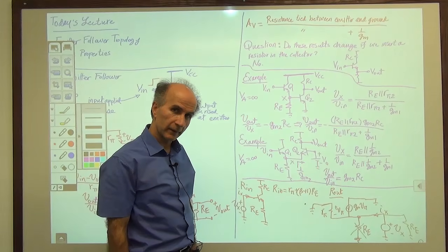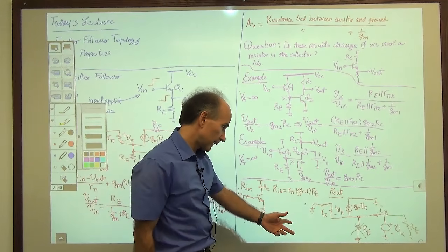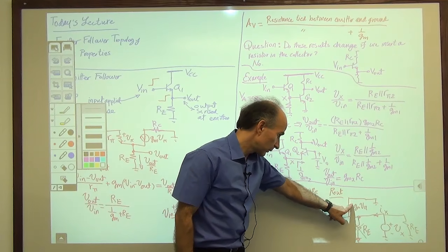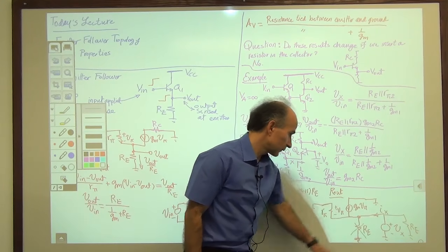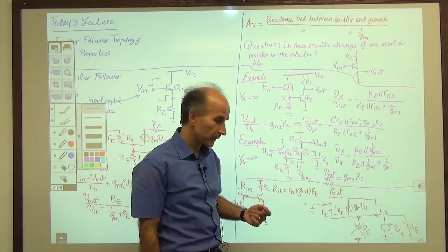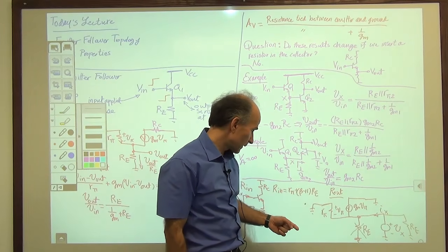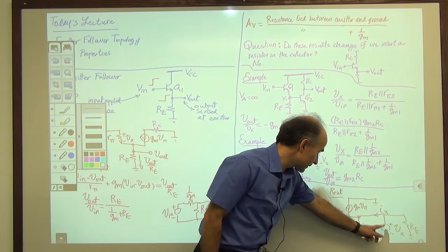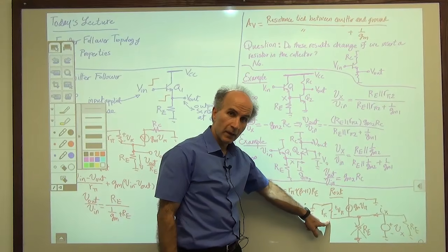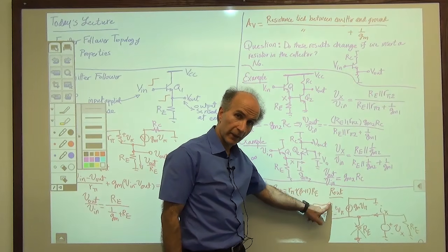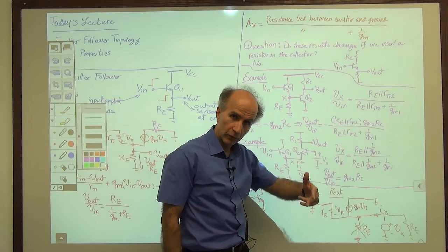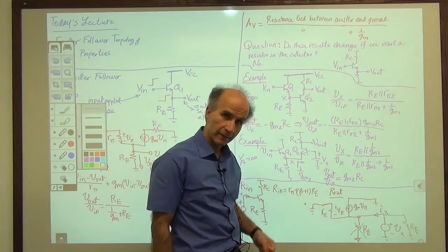Okay, how much is that? Well, we just write the KCL. We have V pi over R pi plus gm V pi equal to minus Ix, or the three add up to 0. And we also notice that Vx and V pi are related. They're both in parallel with R pi, except that V pi is flipped, so V pi is equal to minus Vx.